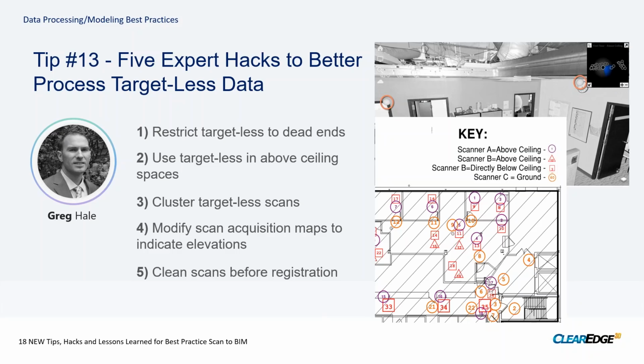A second scanner was on an elevated tripod on a dolly, with wheels, so we could push it through the building and elevate it directly in the middle, or even with the ceiling tiles, popping a ceiling tile and getting it halfway up in there. And then a third scanner, which we mounted on a custom-made board, that you can plug up into the ceiling and then lay on the ceiling tiles. That way you get a double set of scans at the same time: one halfway up in the tiles and the other fully up in there.